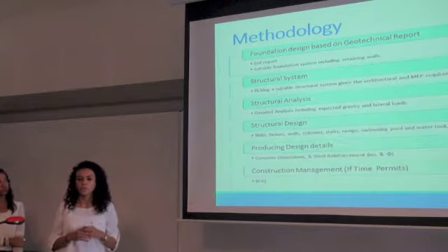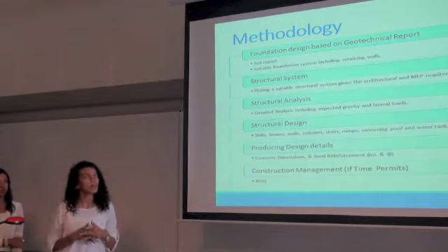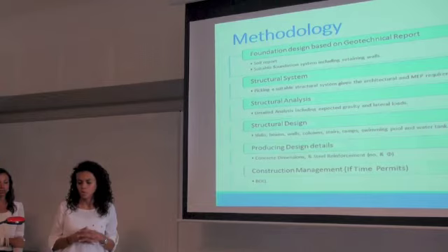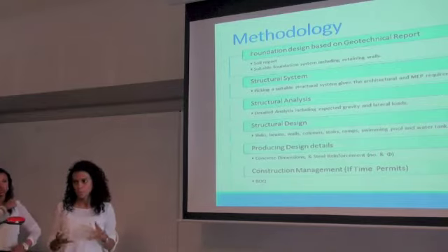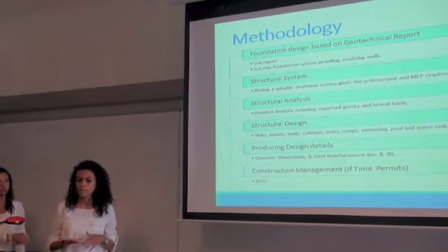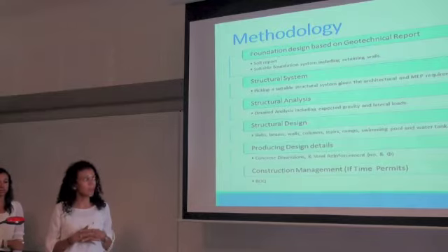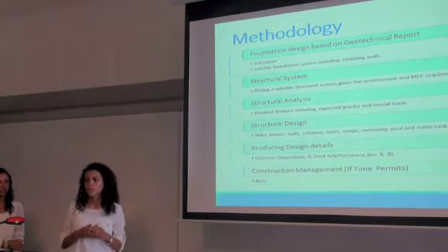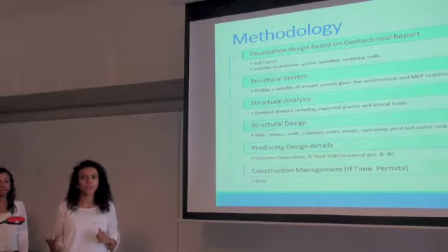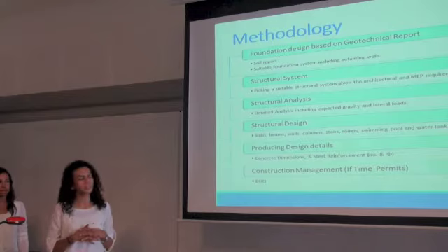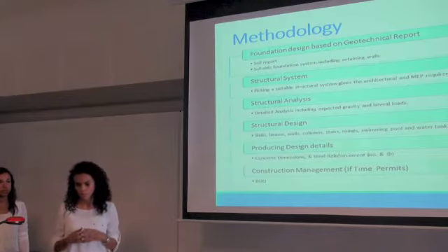Regarding the methodology, the first step is, based on the soil report that we will be obtaining, we'll do the foundation design. The structural system will be picked depending on the foundation that we choose, and as Saif said, we have a lot of freedom regarding that topic. Regarding structural analysis, there are new programs that will be used, which include SAP and ETABS, with which we want to study the gravity and the lateral loads. For the structural design, we'll be covering the main structural elements, which are the walls, the beams, and the columns. In addition to that, we'll be doing the design of the swimming pool and the design of the water tank under the building.